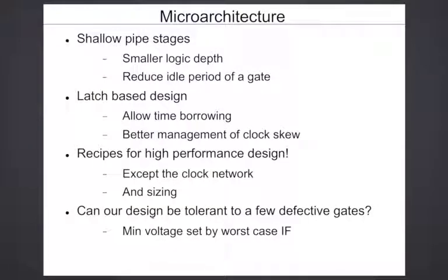Regarding the small slices, we can borrow some time, but in that time the output may glitch due to unequal path delays or something. Will it not create unwanted glitches and extra dynamic power consumption? Yes, the unequal delays leading to dynamic hazards will lead to extra power consumption. Absolutely. In that duration, the signal may switch.